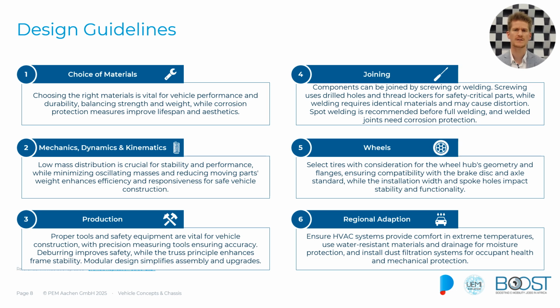Aluminium, on the other side, is not as strong as steel, but therefore a lot lighter. It also has not the same issues with corrosion, so it's a little bit less problematic in that area. But for sustainability aspects, you probably have to put more energy into the creation of aluminium, and the repairability is also an issue compared because not every aluminium alloy is as easy to weld or as easy to repair than it is probably with steel.